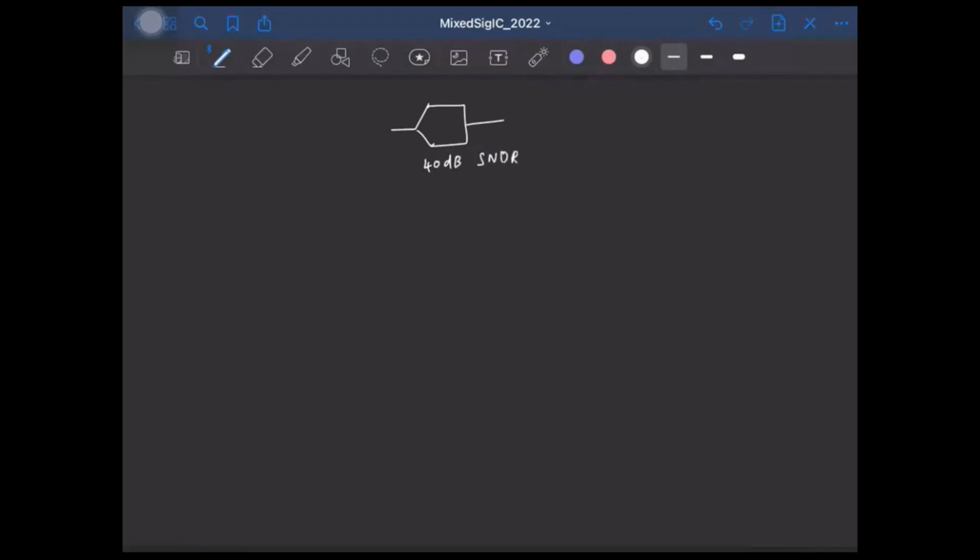Right? And I feed an input sinusoid such that after sampling, it has this form, that is cos 2 pi times 1000 by 3000. Okay. And say I take 3000 samples of this, that is 3000 samples of the ADC output, right? And find the power spectral density using a 3000 point DFT. Okay. So let's see what we get.